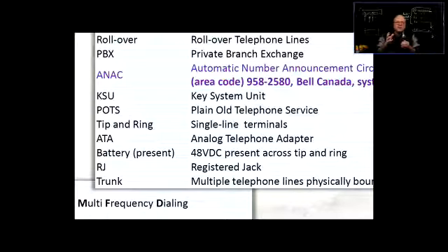If you want to translate this type of signal that is produced by the telephone system, and there's another piece of equipment that doesn't understand the signal of that particular telephone system, such as a paging interface, and paging interfaces are usually configured in the form of POTS, so they understand the POTS type of signal. So if you connect that into the system, those things are not going to talk. So you have to have something in between that translates the signal from one to another.